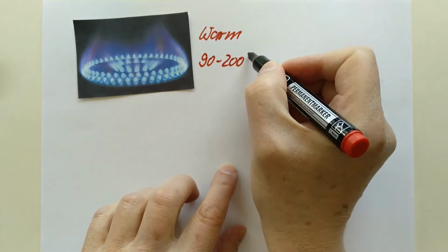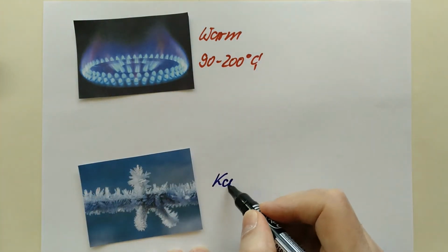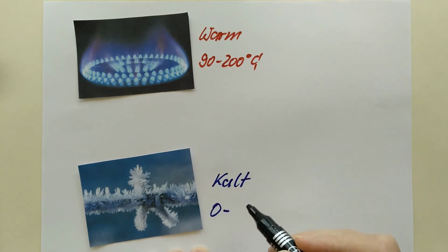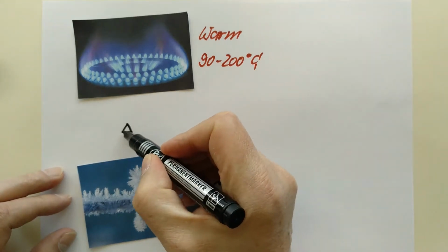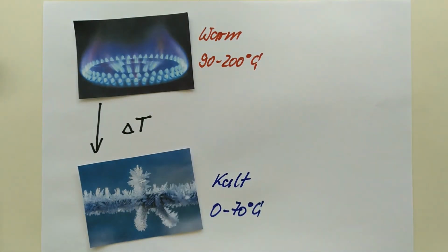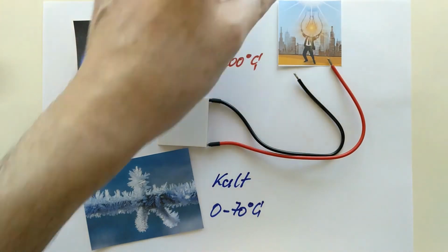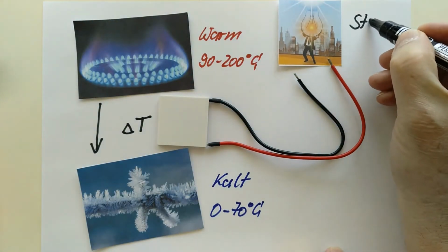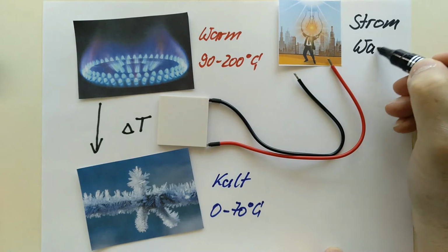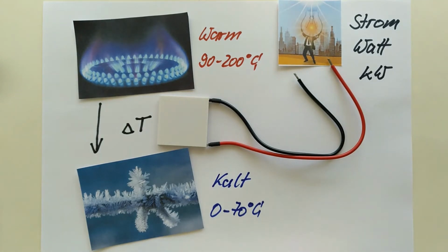All these technologies that convert electricity from heat have one thing in common: they require a temperature gradient. This means that a source with a high temperature level requires a sink with a much lower temperature. For the thermoelectric generators, this means that its output depends on the differential temperature. With each Kelvin degree, its power increases.